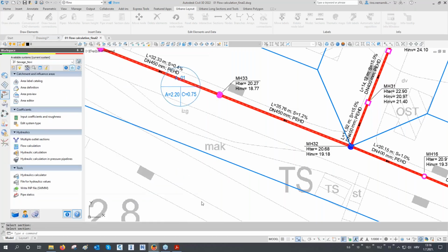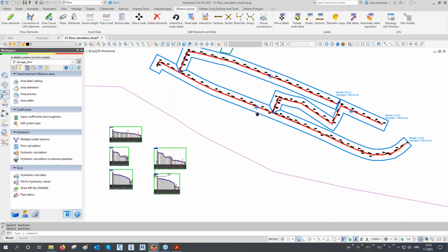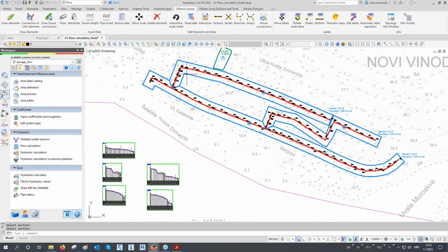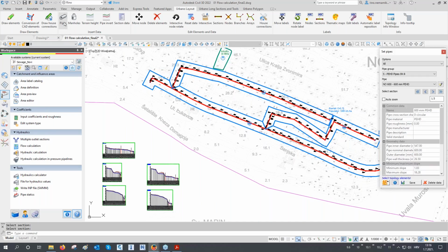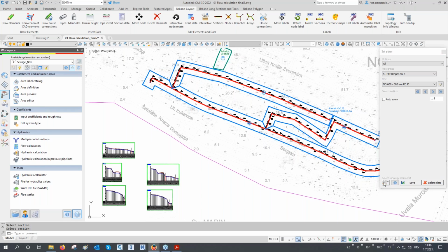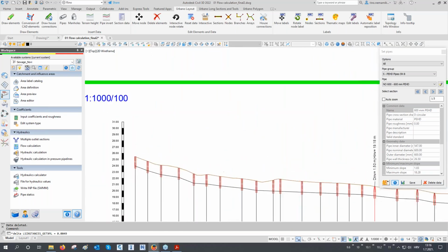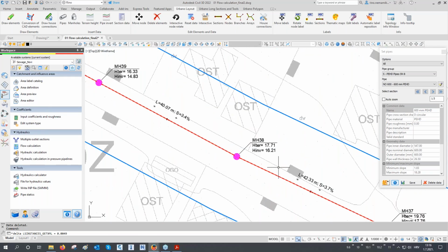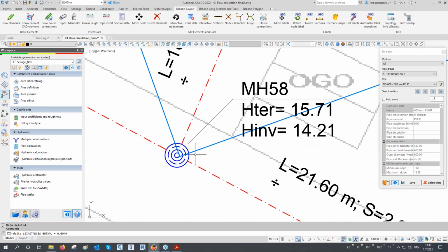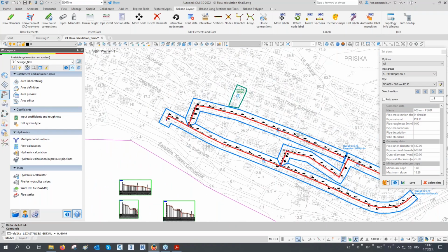But also, we yesterday defined the pipes here. Just randomly, I was showing you the function for setting the pipes. But now we will do real pipe sizing. Of course, I can just run the pipe sizing and the pipes will change, but I would like to delete them so that we have nothing. Let's just select everything and delete data. Okay, so you see that there is no pipes anymore. We reset the pipes. You see how the style automatically updated as well.